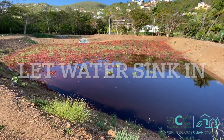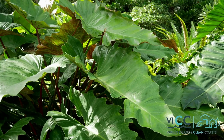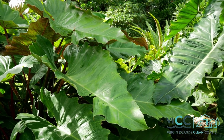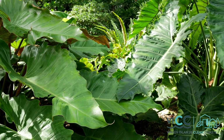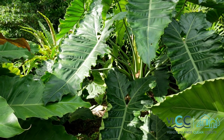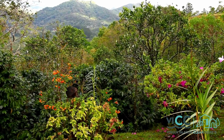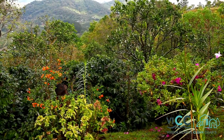Let water sink in. When water is absorbed into the ground, this is called infiltration. Rain gardens are an excellent tool to use to get water to infiltrate. Make sure your soil absorbs water by doing a quick infiltration test. If your soil absorbs water, install a rain garden.